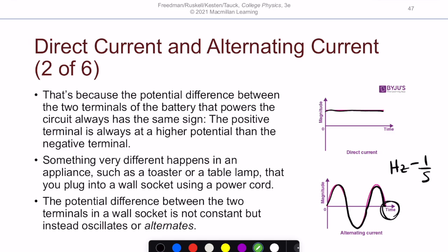It gives me the model number, and then it says the input is 100 volts to 240 volts, 1.5 amps, and then there's a frequency at the end. It says 50 to 60 hertz. So it's expecting me to input an alternating current that alternates at a frequency of 50 to 60 hertz into this device. And what comes out, if you keep reading, is output 5.2 volts, 2.4 amps.